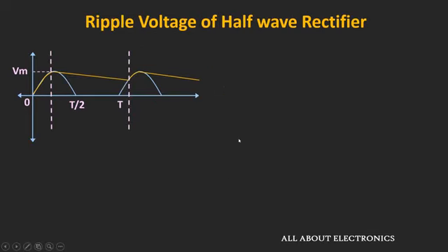waveform. So in this waveform, once the capacitor charges up to this voltage Vm, then it will get discharged through this resistor R, and during the discharging, the voltage across the capacitor can be represented as Vm times e to the power of minus t by RC. Now here, let's say the time which is required by the capacitor to reach from the maximum to the minimum voltage is equal to T1. And let's say this T1 is roughly around capital T, which is the time period of this output waveform.